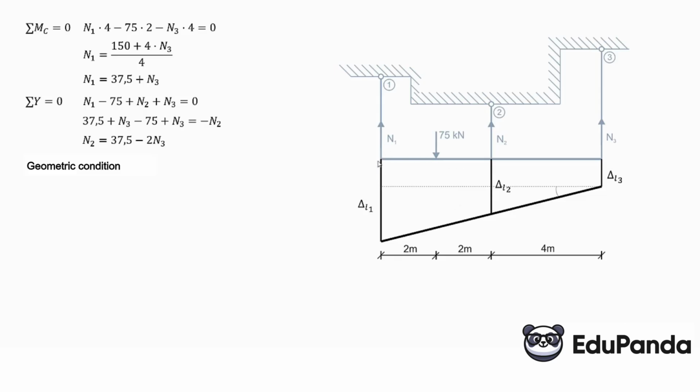Of course, this is all redrawn on a large scale, to make it more visible. So this entire segment is the elongation of the first rod, which is delta L1. And here this cut dashed line is delta L3. So this length that we want to take into the relationship will be the entire delta L1 minus delta L3.